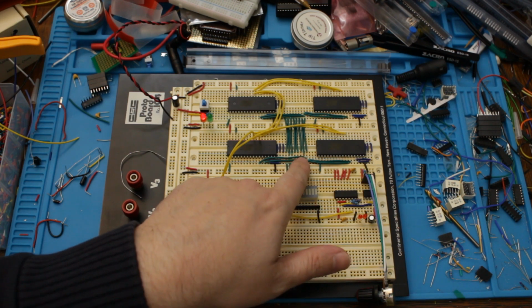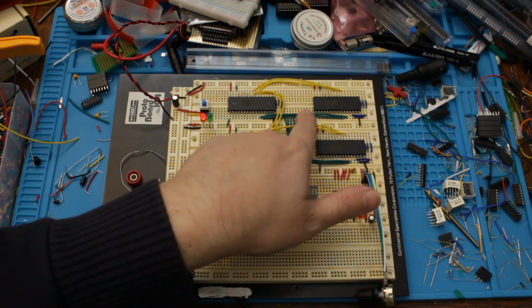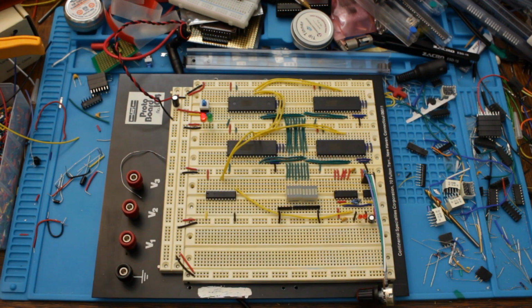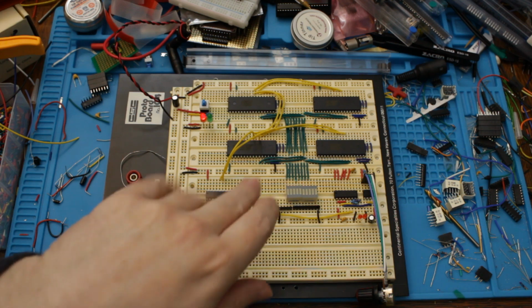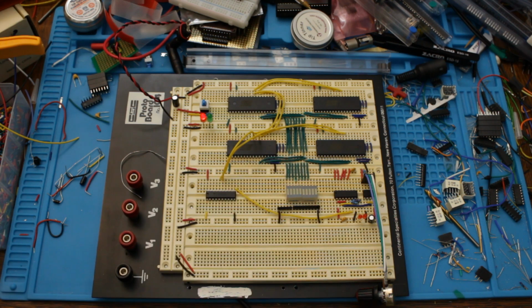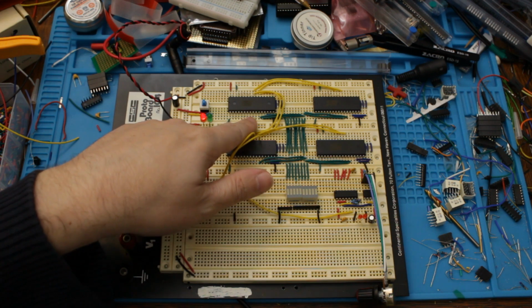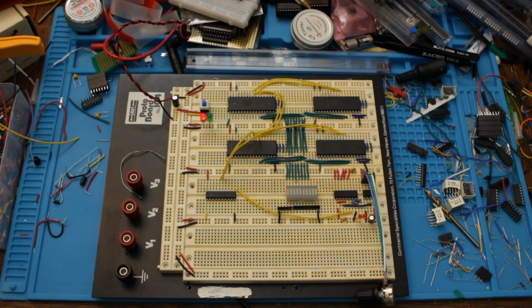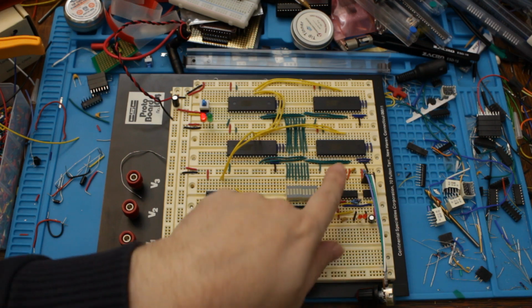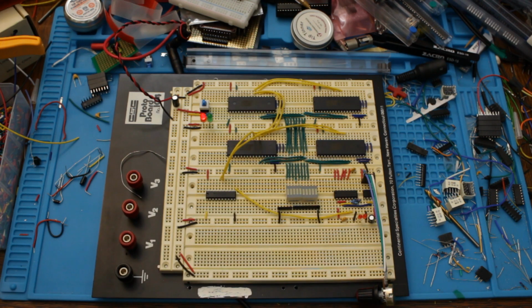I only wired 2 of the address bus bits to each EEPROM, and this means that they can only see 4 unique addresses. All the other address pins on the EEPROMs are grounded here. You probably can't see very well, but I've used lots of tiny little wires here to tie them all to ground. This is just because I didn't want to do lots of address bus wiring for this video, and that's absolutely fine so long as I keep my program to only 4 instructions.